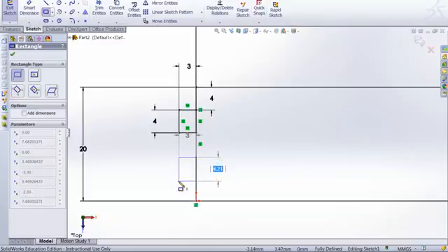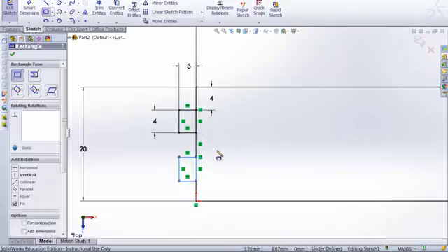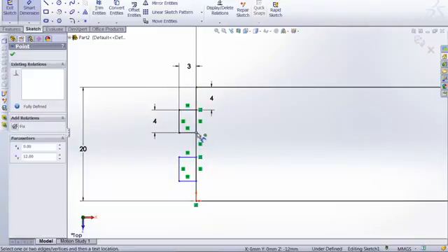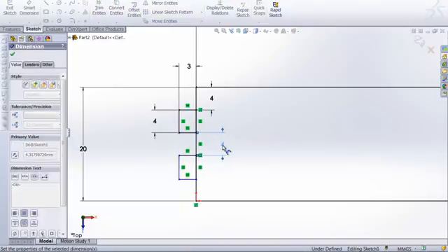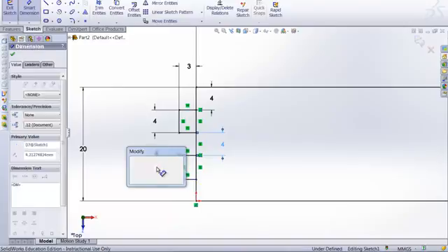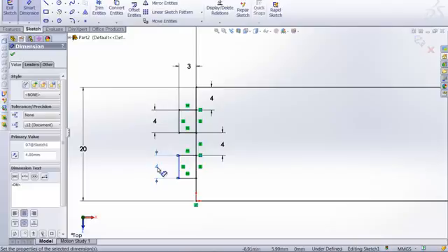Okay, that's great. Next thing I want to do is of course to tick this here and use the smart dimension again. And now I know I first need to define, so click this point, make sure that is 4 millimeters. And I'm also going to click this point and this point and move to the left, click one more time, type 4 millimeters, but it's still underdefined.